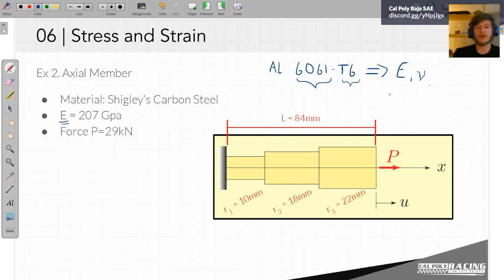It's got some E, some tensile strength, some Young's modulus, some Poisson's ratio that is generally known. If you have some more exotic materials or manufacturers that are trying to get an edge, then they'll provide you specifically with their test results. This isn't as common anymore because, especially for the common materials that we build with, there's a very wide market. But not that long ago, even 100 years ago, some foundry in some part of the world might have some special formula for their steel that happens to be a lot stronger.